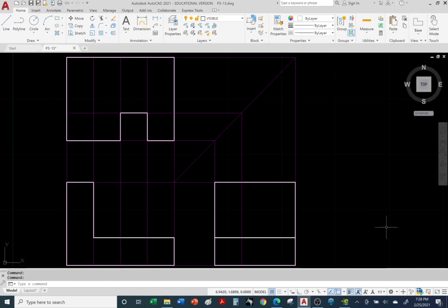Those of you that want to turn on or turn off your dynamic input: anytime you use a command, for example, we're ready to use the line command, click on the line command. You can type in coordinates if you have dynamic input, so that we can do things on the fly by simply typing in your X and Y coordinates, or you can even type in a length and an angle. I'm going to turn off my dynamic input. You can leave it on if you're comfortable with it.